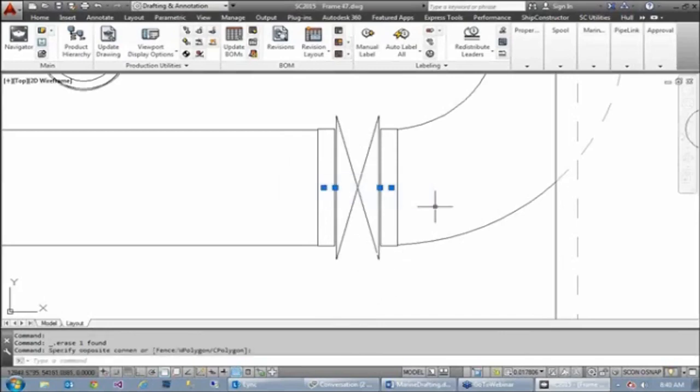And these points that you have here are shown for the connection. So if I wanted to show actual accessory package details, I would be picking those connection points, which are just points in AutoCAD. So there's a way of actually being able to show the connection accessories in a bill of material and have them labeled here if I really wanted to. So that's why it's showing those. It's one of the output options I have.